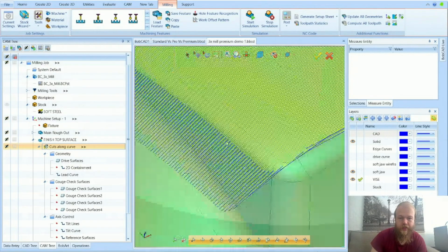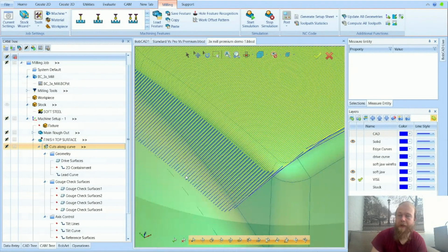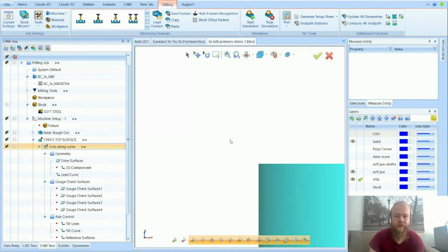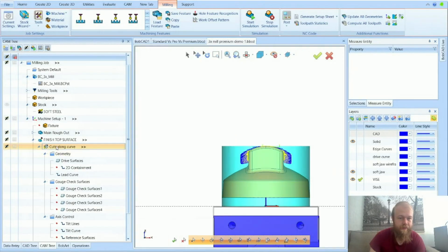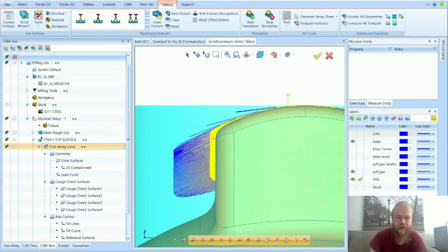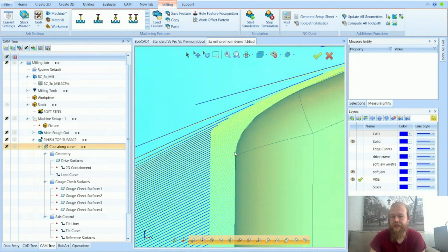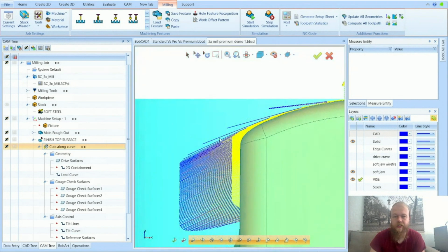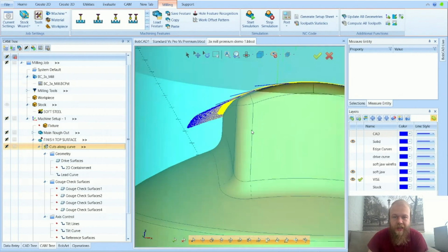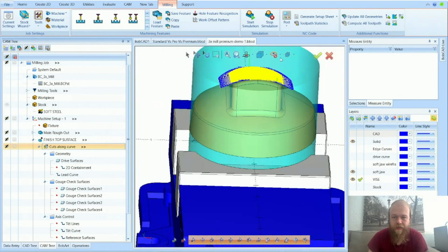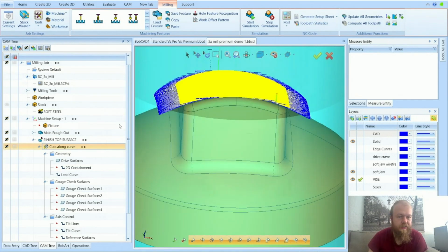So here's your 1/2 inch tangential extensions past the surface. And we can see from the side view here that it follows the surface itself. It doesn't follow down the surface of this fillet. It just goes and extends tangentially across the end of the surface that we have. So that's our tangential extensions.